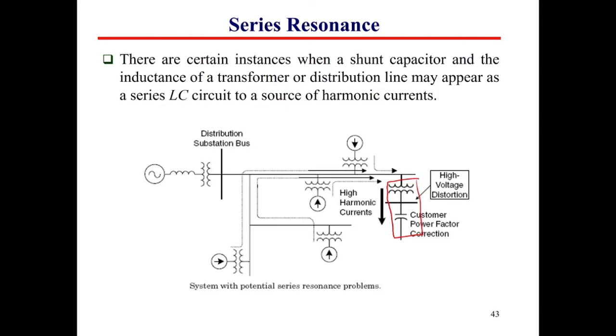That means when we design this system, with the capacitor bank and the transformer, if we choose a proper value of both L and C, that can short circuit all the harmonics, so the harmonics will not affect the load that will be connected after this place.